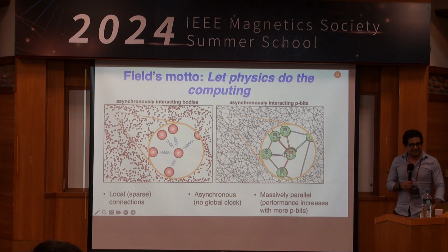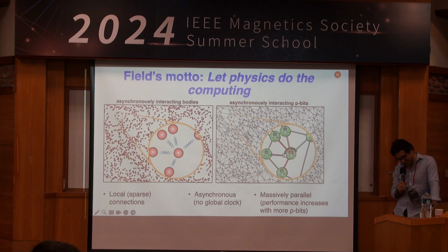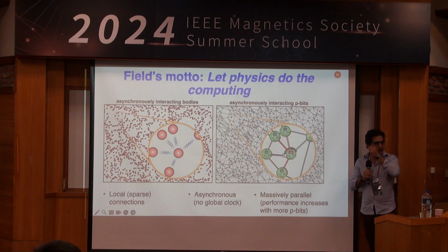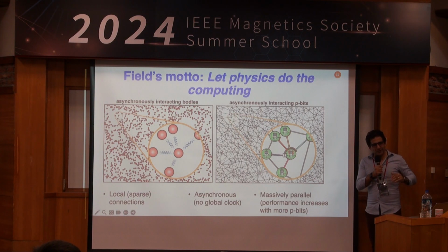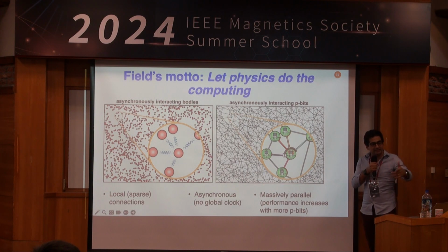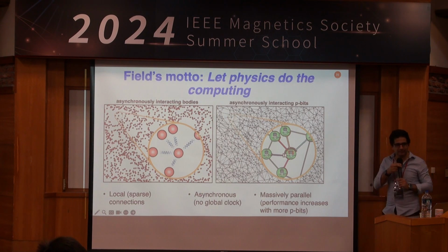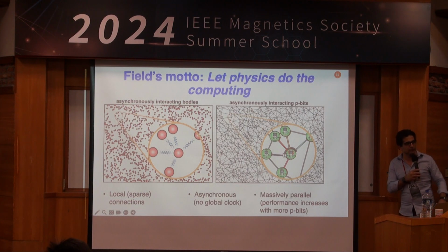When you're solving the inverse problem and you fix the answer, do the solutions also fluctuate at the same time scale? Yeah, that's a very good point. We do what's called simulated annealing. In experiments, people anneal their materials, right? So you start from a high algorithmic temperature. In the conductance example in the simplest p-bit circuit I showed, we start from a low conductance and increase it over time. By the time you find a good answer, you don't want to lose it because the p-bit is just going all over the place. That's a good point that I did not mention at all, but those are the types of things you would have to do.